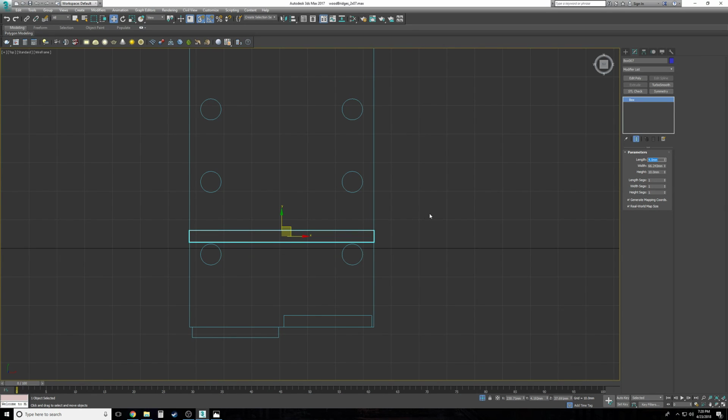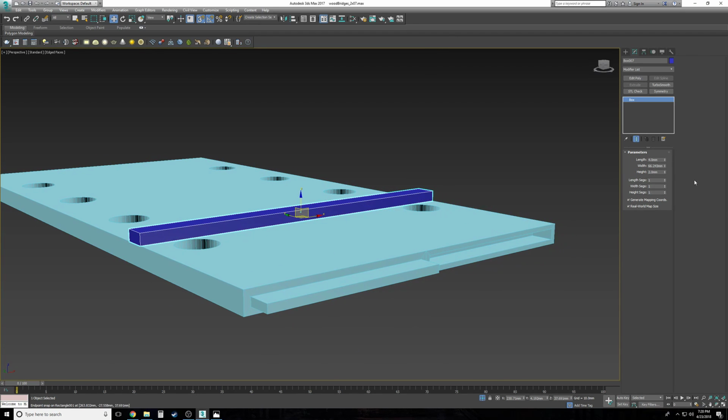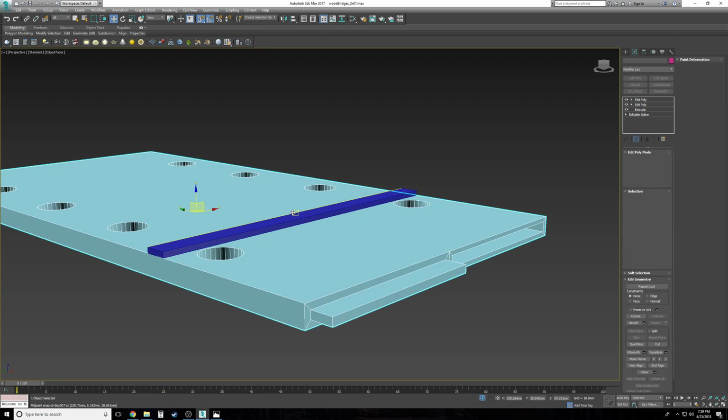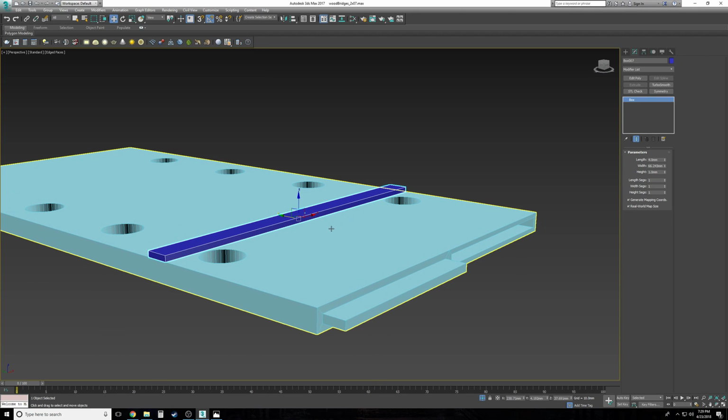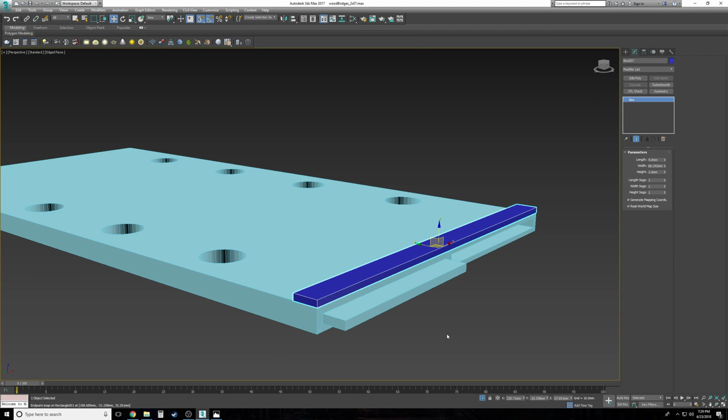And let's make these 4 millimeters in length, and we're only going to make these like 2 millimeters tall. That'll be just not even that, maybe 1 millimeter. That looks better. That's going to be 5 layers. So if you print off, I usually print off 0.15 millimeters per layer, which means you get a lot of layers before you get 1 millimeter. And that's 1 full millimeter, so that's going to be strong enough. So let's put this thing right there.